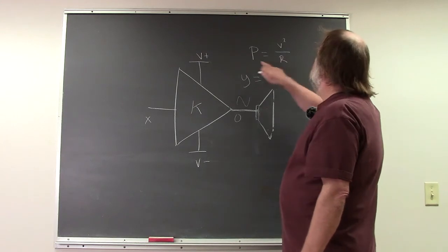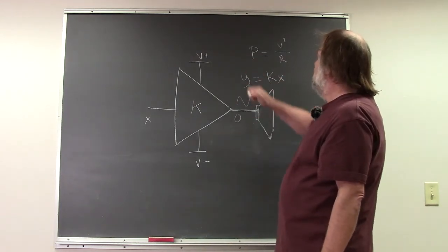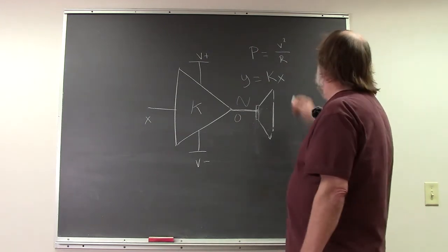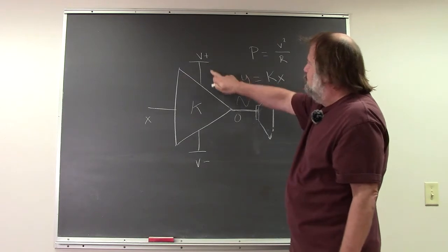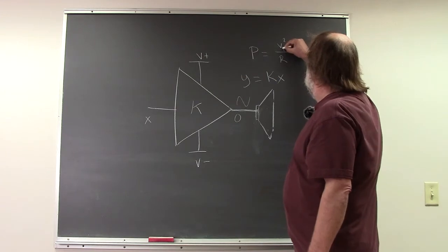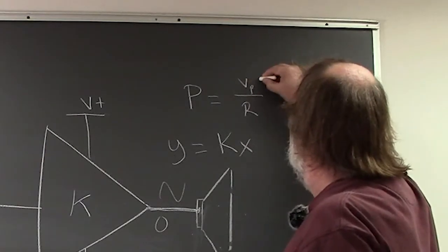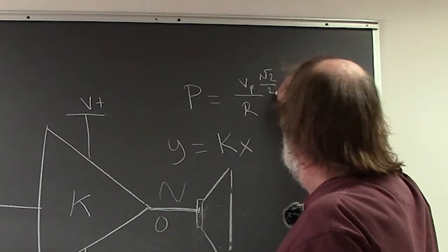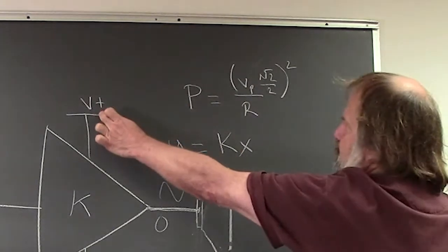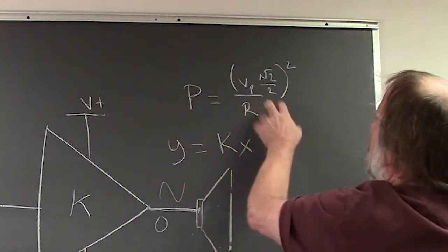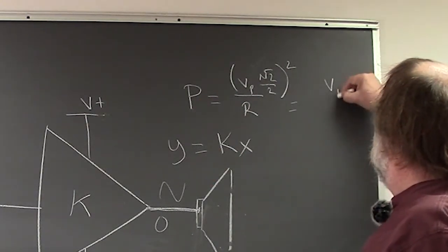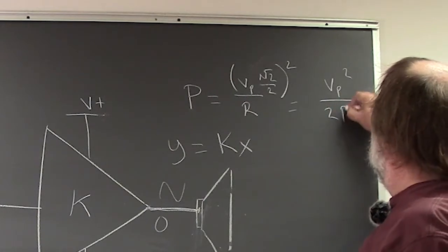So one of the things I don't like about the way we think about power amplifiers is that it's actually more useful most of the time to think about how many volts it swings. And you can calculate that pretty easily, because if you know the supply rails, or more importantly how far the amplifier can swing, that's the V peak, and that's actually related like this, which is how to convert peak, assuming this went to the full rails, in this case V plus, and we multiply it by this, and if you do the math here, this will be V peak squared divided by 2R.